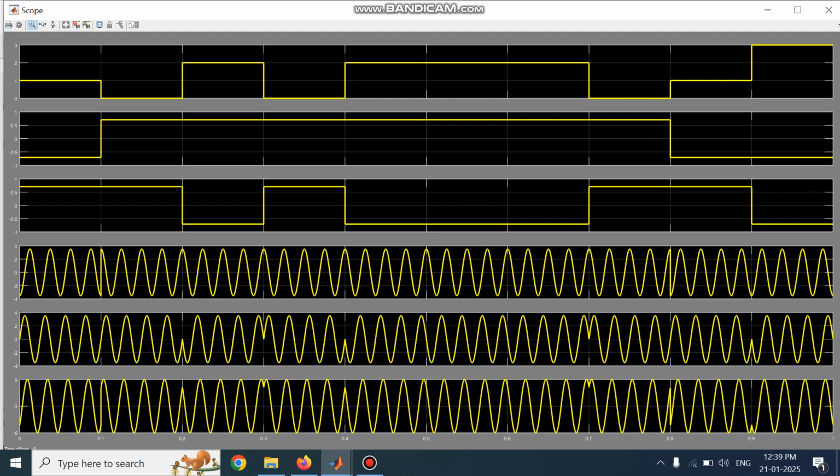Once these signals are generated, we have to combine them using an adder. The resultant signal is a QPSK wave. Now let us check. So this is the resultant QPSK. As you can see here, the first integer is 1. The corresponding odd bit is 0, even bit is 1. As per our previous discussion, we have to represent it by 5 pi by 4. So this is 225 degree. If you refer to this point, with respect to cos, this is a 225 degree phase shift.